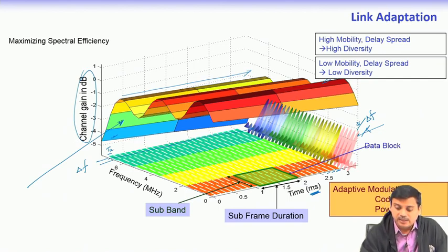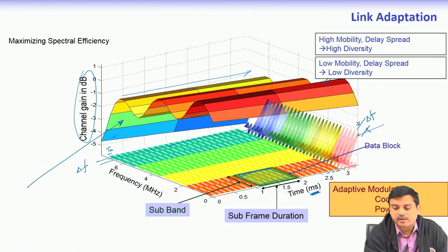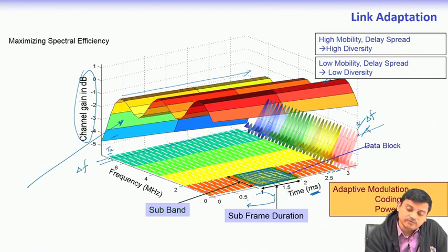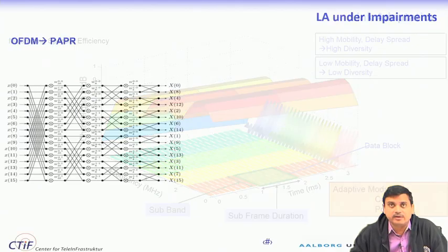And as we have said earlier, that several such OFDM symbols in time are grouped together, and several such subcarriers are grouped together to form a resource block, as has been marked by this color, and I am putting a shade on this, which is the resource unit on which all kinds of link adaptation procedure is done. So, this unit in its multiples have to flow from transmitter to receiver for estimation, receiver to transmitter again for feedback information, and then it has to go. So, this needs to be understood. We will get back to more detail on performance analysis again later on.